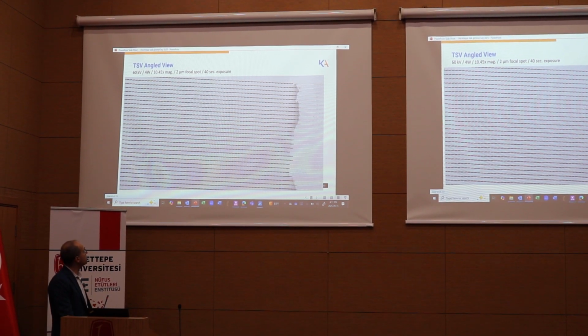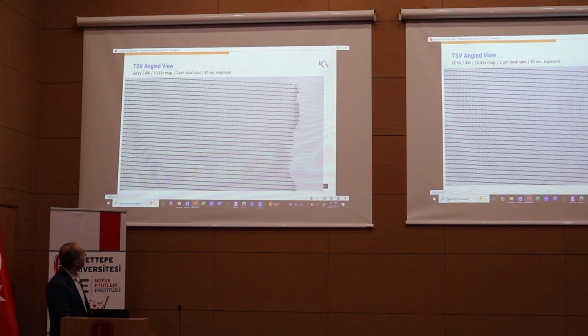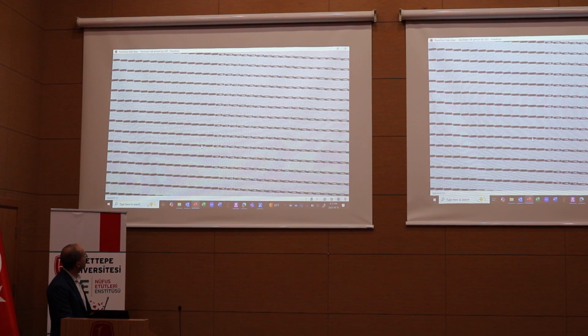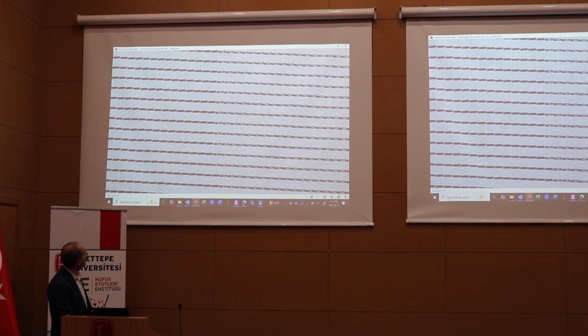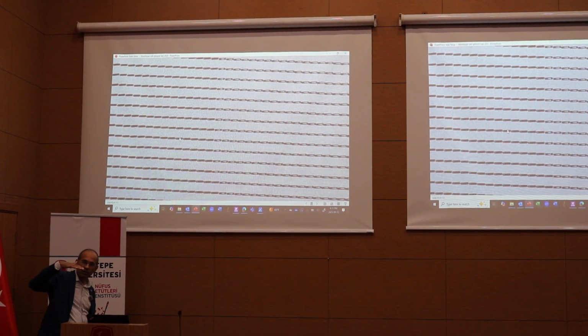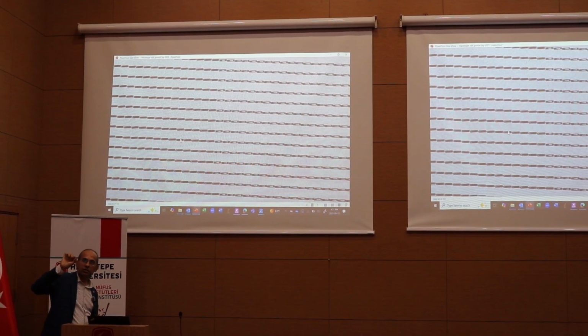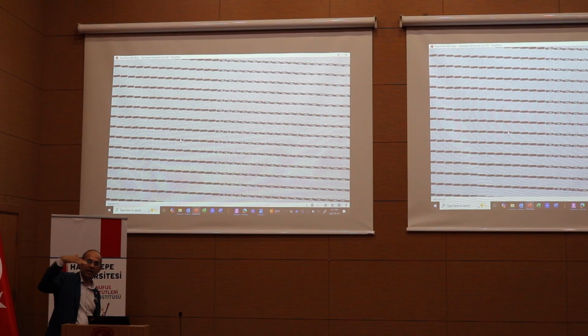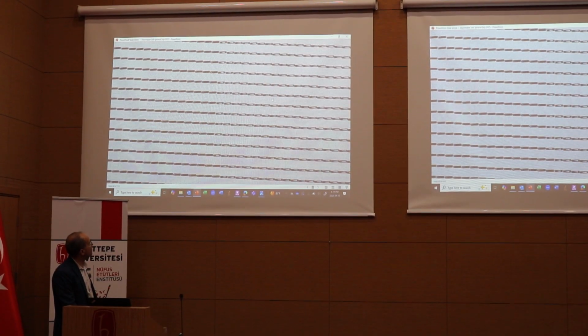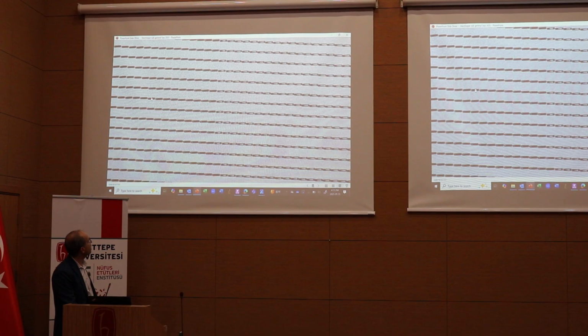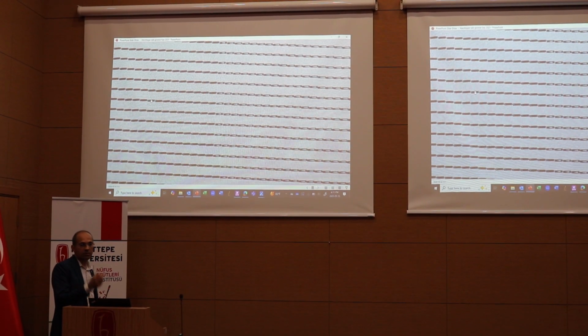Again, each of these vias is probably 20 to 30 microns, and you can see the fill quite easily, because if I zoom in, these vias are full. I had to take the shot at a 3-degree angle because otherwise it just looks like a dot. At least now I can see the side of the via. But you can see the vias on the right are not filled, and the vias on the left are filled. Great way to be able to do electronics.